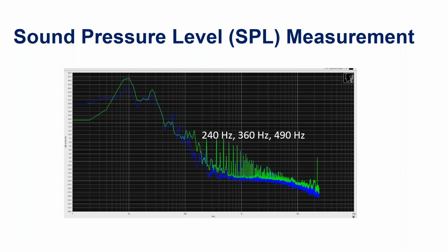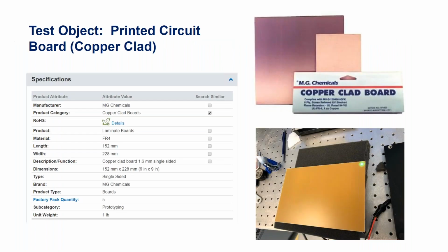And if it's a buzzing component from it being powered up, here you have harmonics of 120 hertz all the way down the spectrum. And this creates a buzzing noise that can be undesirable, something you want to get rid of or at least reduce the effects of. So this is the problem. This is the general approach using microphones.